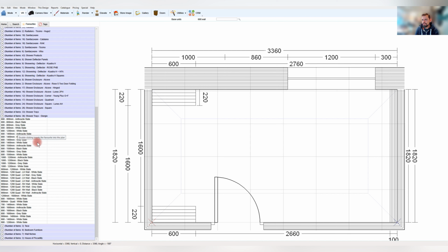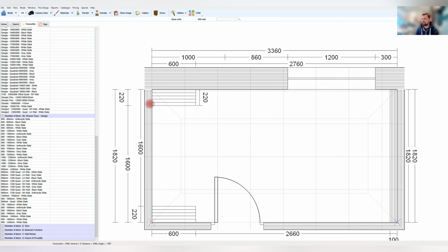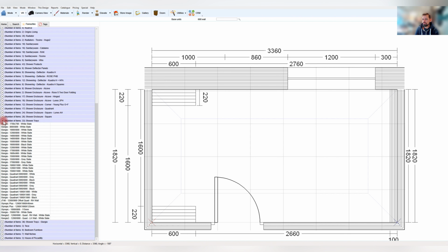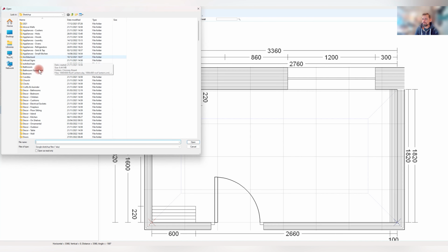I need an 1800 really, so I've probably created it in the other. No, I have no 1800s there. Okay, I'll tell you what, I'll import one I've already done so I can just get on with the design, otherwise it will take ages. The one I did previously, I've made every single size. Just I've been polishing them off and adding radius ends on them just to make them a little bit more realistic. And the fold starting within 100mm from the edge rather than straight from the edge. Again, just for the realism.